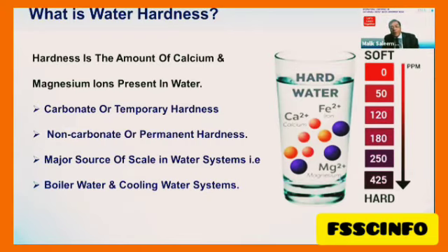Similarly, when we go to industry, various processes require specific water, especially heat exchangers like boilers and cooling towers. There we have scale formation, and we need to keep the surface clean to have good efficiency of the boilers and the heat exchangers, because where the scale deposits, no transfer of heat takes place, or very poor transfer of heat takes place.